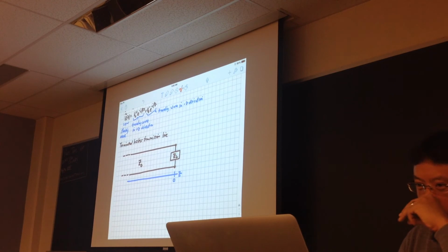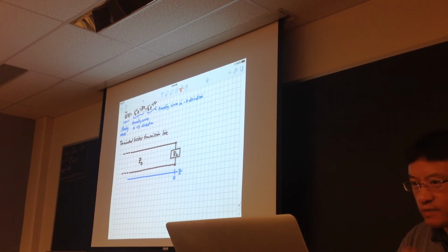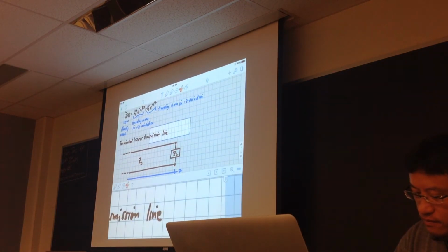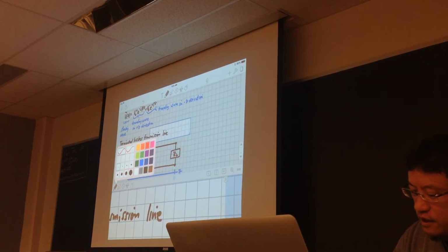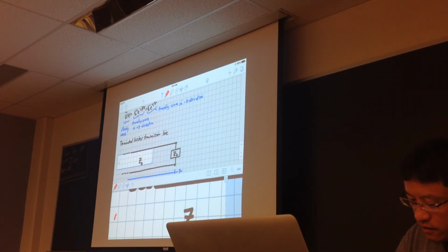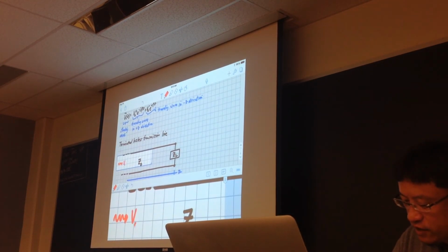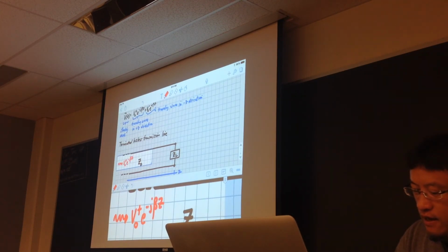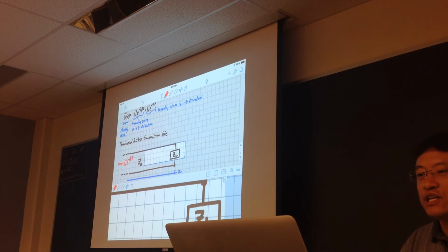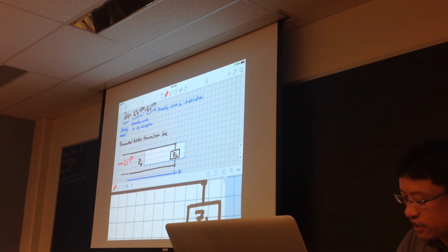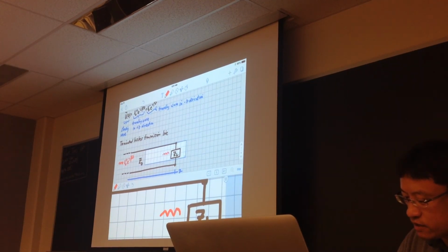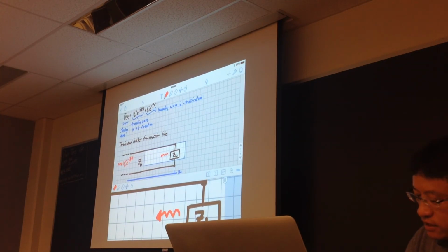The way to think about this is you've got a wave coming in on your transmission line. Let's say that's the V0 plus e to the minus j beta z term. Then, depending on the value of the load impedance, you're going to get some kind of back reflection, which will be the minus z traveling wave.